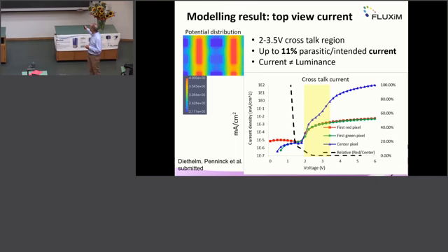If we define a ratio, the black dashed line is the ratio between the red and the center, so red and blue pixel. We see at low voltage this percentage can be almost 10% or 11%. So just above turn-on, we have a very high, 11% contribution of red light in the display, and that becomes visible as a color change to purple-blue instead of pure blue.